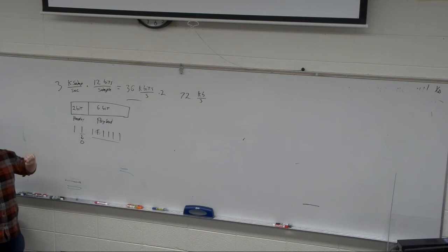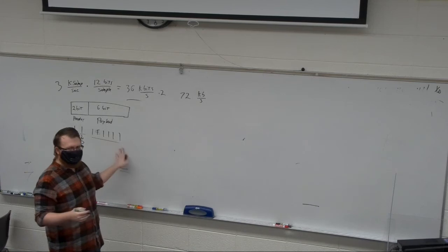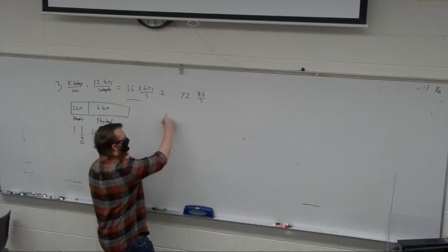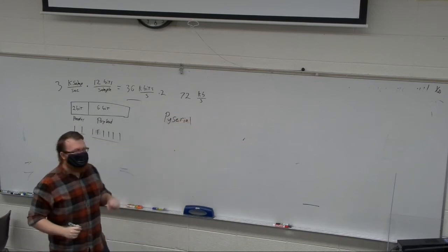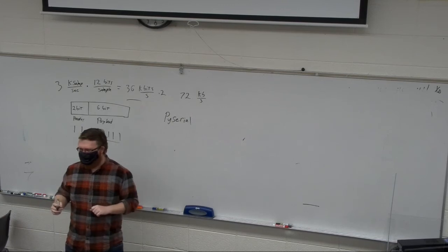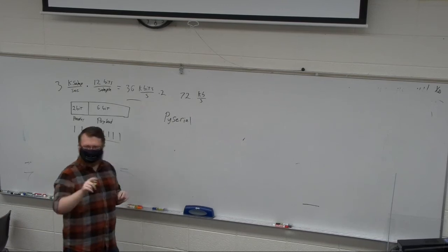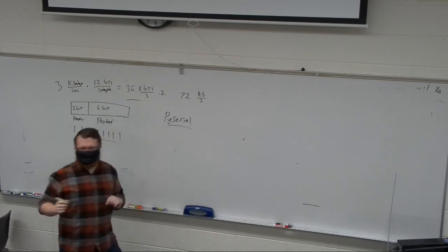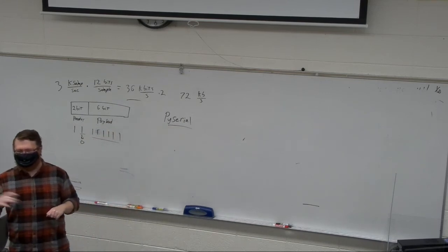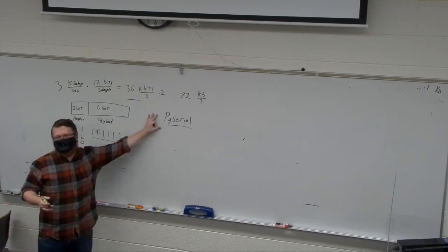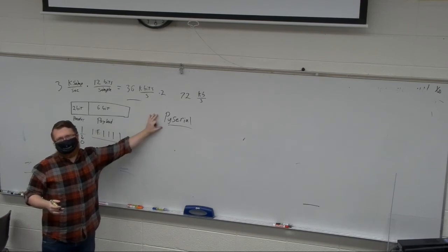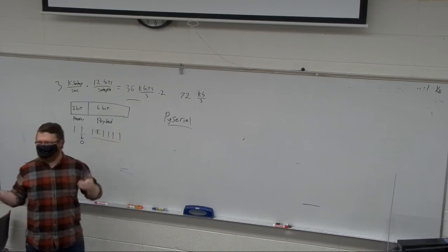Yes, you definitely want the 2-bit header in this case. You can set up Python fairly easily if you want to do it another way. Python has the PySerial library. If you would like to do this the proper way, and I encourage you especially to do this, use PySerial instead of the log on PuTTY to save that data. We just need some way of saving the data. PySerial makes this pretty easy. Its biggest challenge is when to start and when to stop, essentially. But fortunately, you'll know that, right?